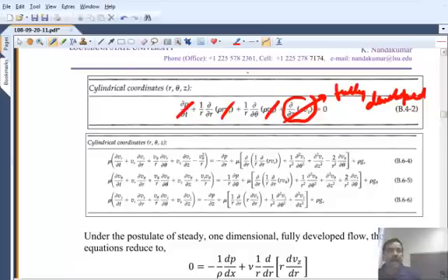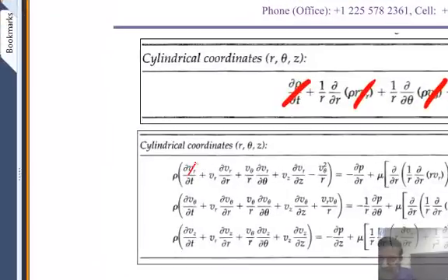If you take the r component of the momentum equation, which will be the r component of the three equations that you see there? How will you determine that? The one that has r everywhere. So all those terms are going to be 0. But notice that there is a theta component in that equation, so don't drop that out. And of course there is no g, because we have absorbed it into the static pressure, so we are looking at dynamic pressure.